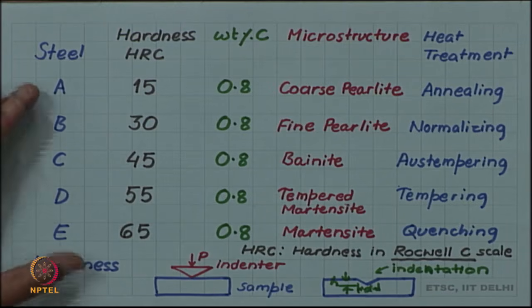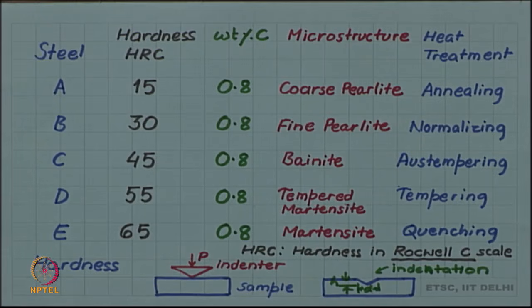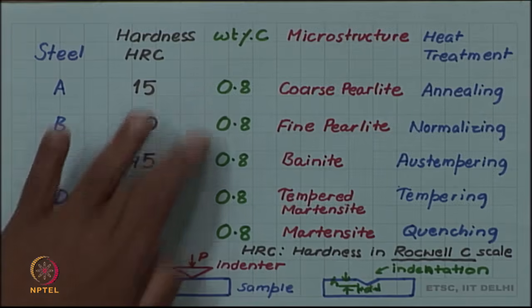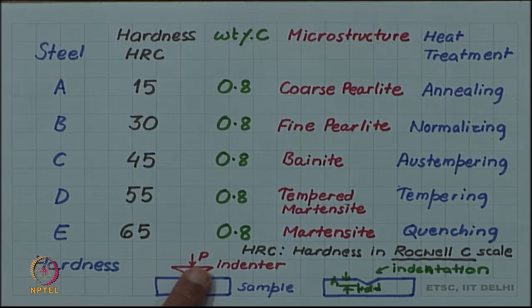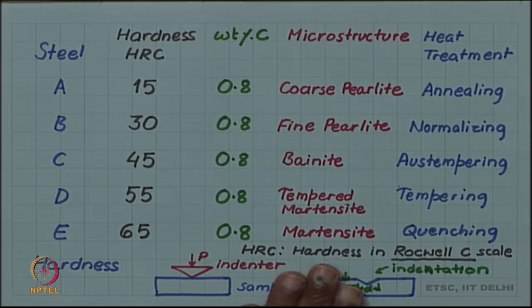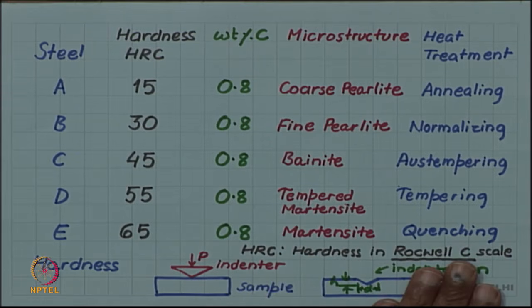And you can see that hardness is a very structure sensitive property. There are properties, for example, if we talk about the density, densities of these steels will not be very different. So, density is more or less dependent on the composition of the material, but here is a mechanical property, even electrical property, some of these properties are highly structure sensitive, and they will depend on the microstructure which we have produced, and thus will depend upon the processing history.